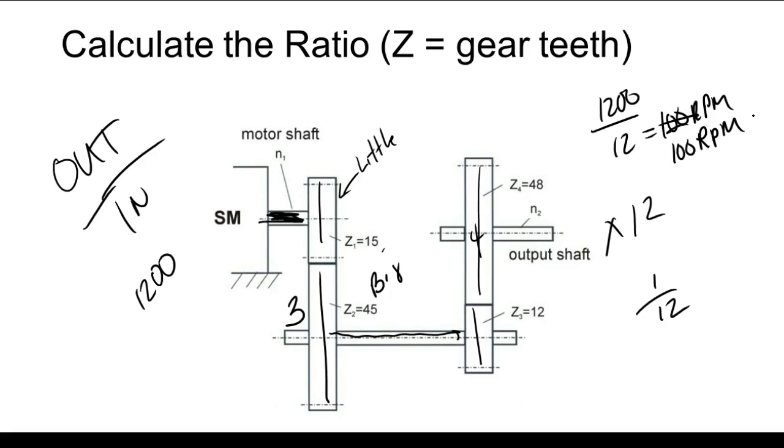In fact, a lot of straight shifts have a tach gauge on them, because you can literally overspeed your engine. You can blow your motor up by overspeeding it, right? You understand? So your tach gauge is telling you where you have to shift. It doesn't mean you can't shift before then, but you're not supposed to shift after it. We call it red line.